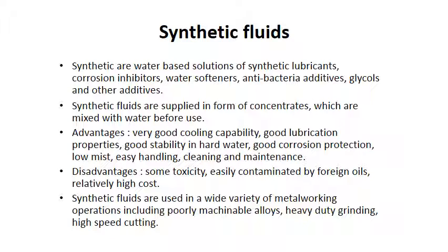Drawbacks or disadvantages of synthetic fluids are some toxicity, easily contaminated by tramp oils, and relatively high cost. Synthetic fluids are used in a wide variety of metalworking operations, including poorly machinable alloys, heavy duty grinding and high speed cutting. You can use synthetic fluids there.